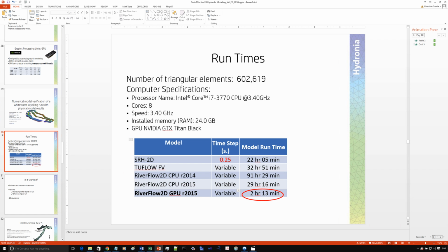And what hydraulic structures can it model? Well, there is another webinar that deals with hydraulic structures, so I can give you the links for those of you interested. For example, bridges. You can handle bridges in 2D inside the mesh, and the bridges can have situations of pressure flow and overtopping. Those situations are accounted for in the tool. You also have gates, so you can define the gate with the sluice gate operation. You have weirs and culverts, and the culverts are used as one-dimensional connections between two different elements. The model calculates the discharge based on the Federal Highway Administration formulations.